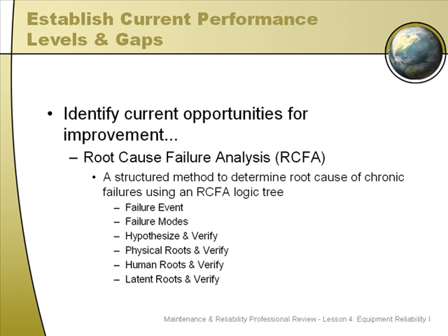Let's take a look at root cause failure analysis, or RCFA, as a method for identifying current opportunities for improvement. Root cause failure analysis is just a structured method to determine the root cause of chronic failures using a logic tree. The first thing at the top of the tree that we would put down on a piece of paper is the failure event itself. Then we would go down one level in the tree and list all of the possible failure modes.